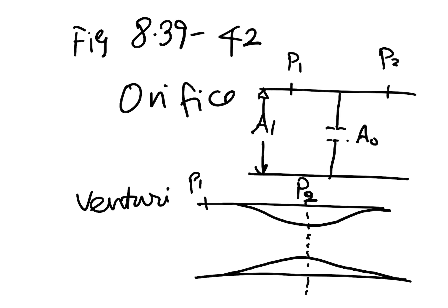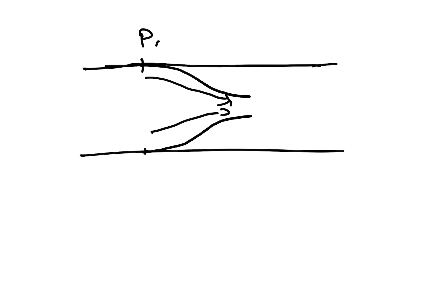And then the other is that of nozzle, where we have a flow constriction and then we tap P1 here and then there is a nozzle through which the flow accelerates and it is let out. The pressure is measured here, P2. So this is a nozzle.